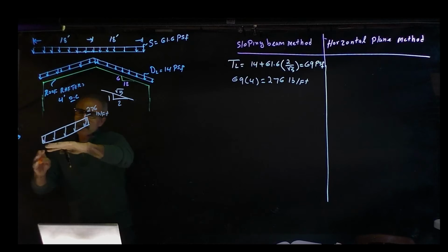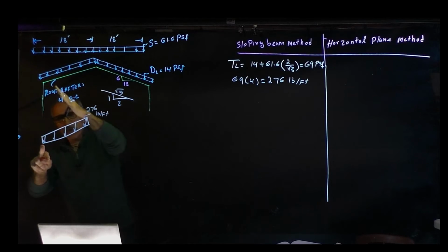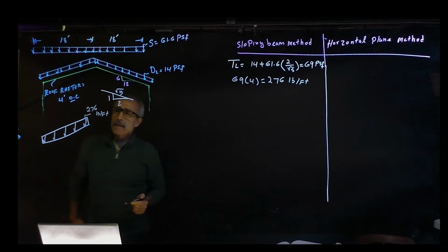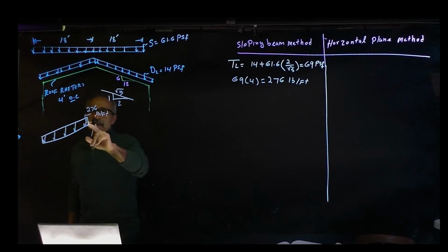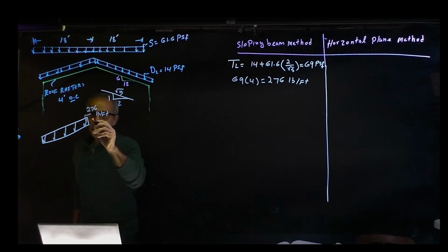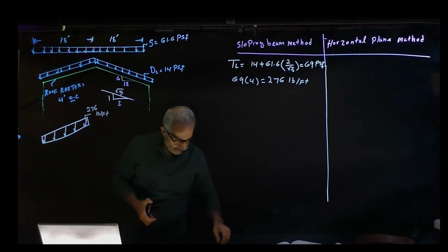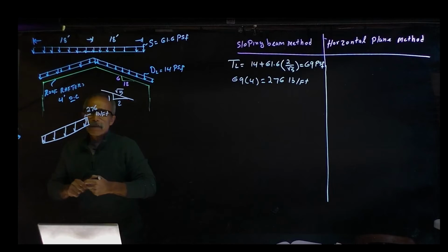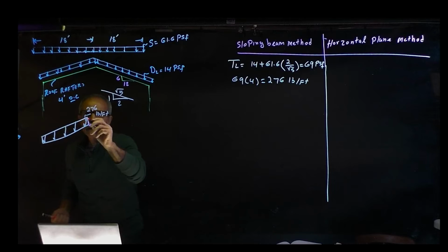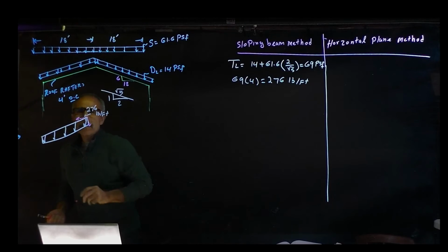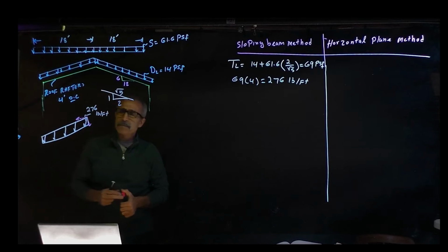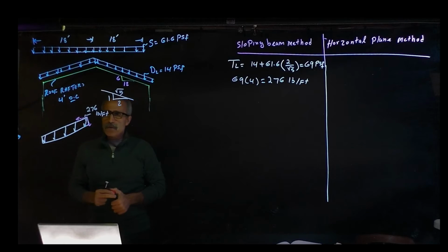Now if I say this is my x-axis, that's my y-axis, perpendicular being the y-axis and parallel being the x-axis, this can convert to those components. So I can take that one load right there. It's going to have a perpendicular one right here, and then a horizontal one relative to this. We're going to go ahead and figure those out.